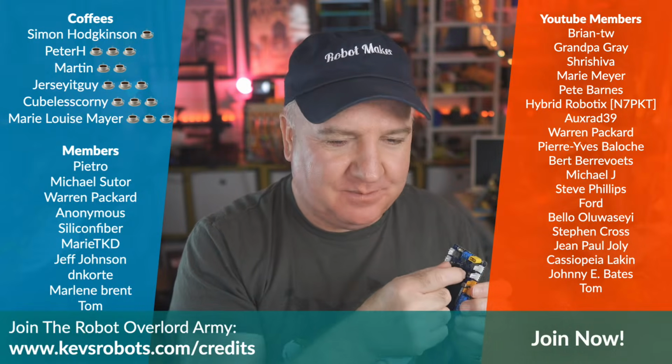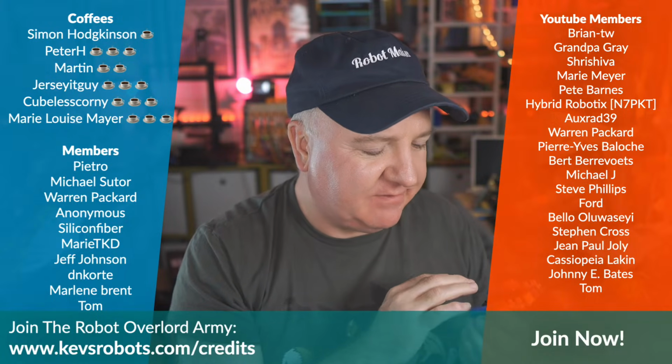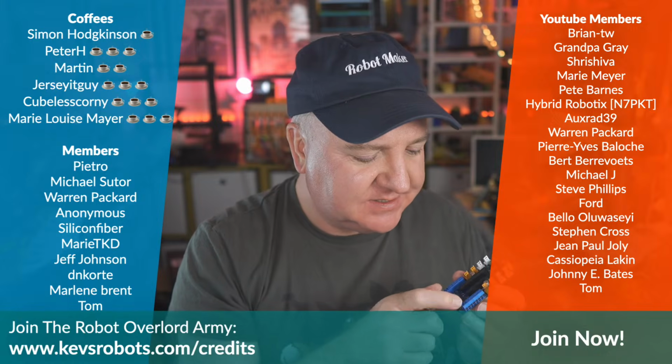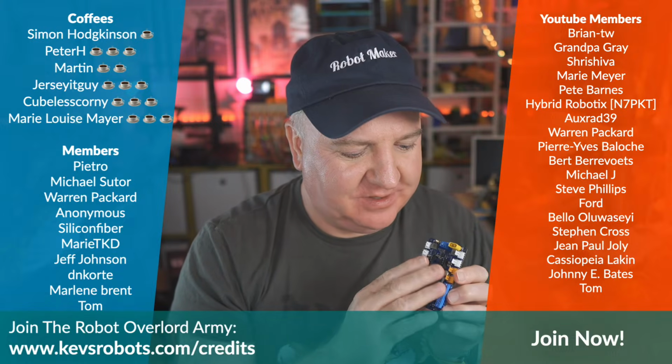It connects from the board using I2C, so it doesn't connect using the GPIO pins. So all those GPIO pins are kind of available for you to use for other things. But it's got all these nice headers, and it kind of offloads the complexity of setting the pulse width modulation and so on for the motors.